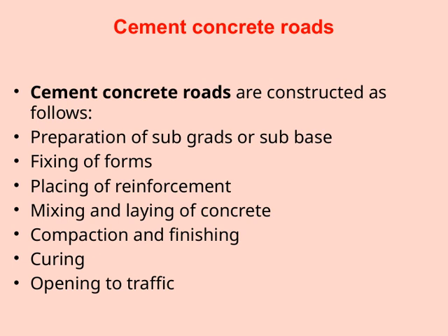Reinforcement is essential because it gives the concrete additional strength and durability, especially under heavy loads. After that, the concrete itself is mixed and laid. This step requires careful mixing to get the right consistency and then pouring it evenly over the prepared surface. Once the concrete is laid, compaction and finishing follow. Compaction removes air pockets and ensures the concrete bonds well, while finishing gives the surface a smooth and even appearance.